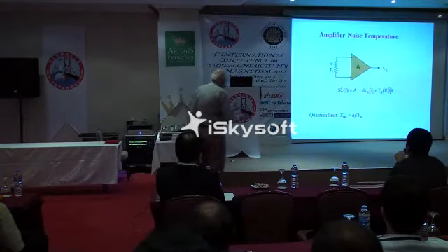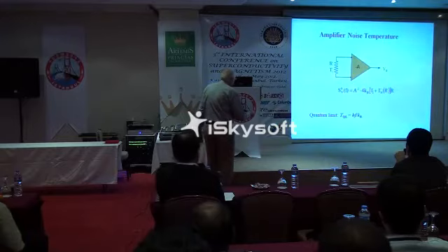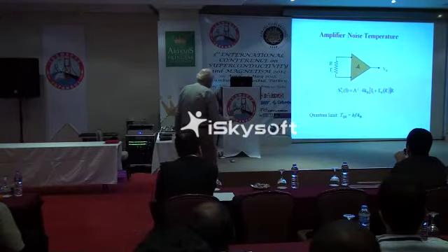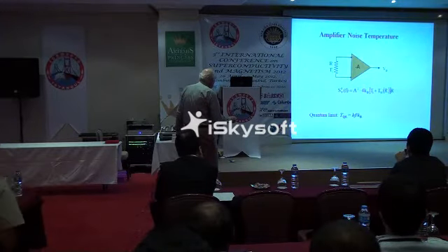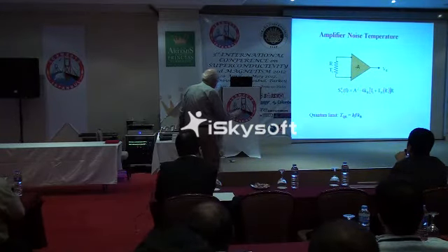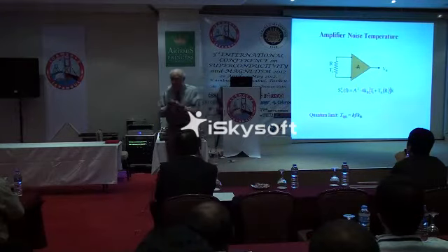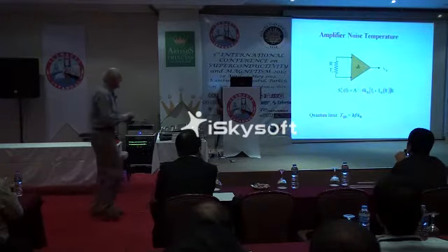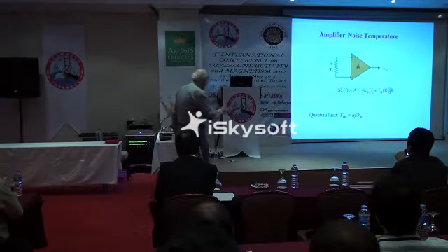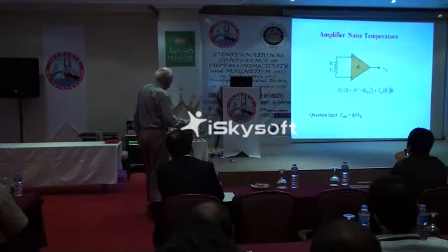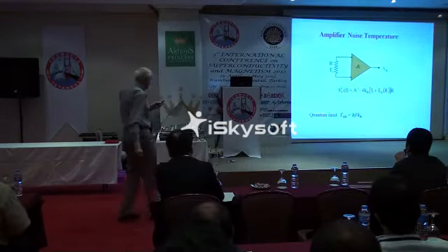And if you look at this spectral density, that is the power in the output, here's the Nyquist noise term, 4 k_B T_i R, but we've added to that a term T_n for noise temperature. And that is the added noise of the amplifier. And it's a very simple, very convenient way of characterizing the noise of amplifiers. And as you can see here, you simply add them together. The quantum limit of such amplifiers is given by Planck's constant times the signal frequency over Boltzmann's constant.